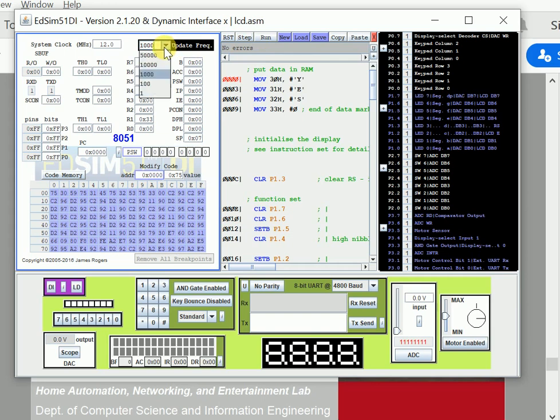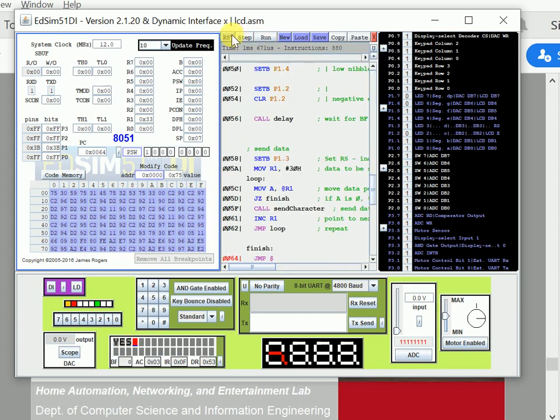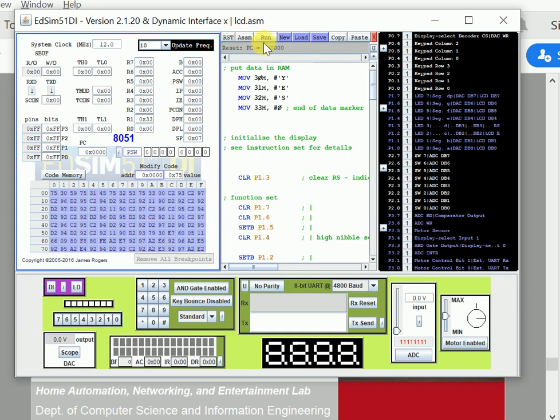Now you run it, and you can dynamically select the frequency also. For example, I have selected a very low frequency, 10 units with respect to 12 megahertz. Fine. And run this program. So you can see currently nothing has been displayed. See, it became red, Y has been displayed, then this became red, E has been displayed, this became red, S has been displayed. See, so easy it is. Pause this, reset it, everything would be reset.